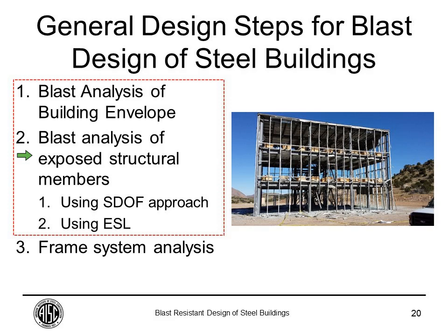When you're designing these members, we're going to look at the single degree of freedom approach. As we mentioned before, we also have closed-form manual calculations, a type of analysis using an energy approach. And we're going to discuss the equivalent static load approach, which is the one used mainly for connections. Finally, we're going to talk briefly about the frame system analysis and just introduce you to a couple of approaches that you could use if you were faced with that challenge of performing a frame system analysis on a steel building.